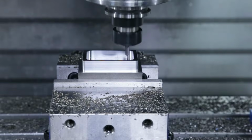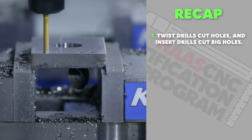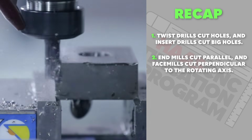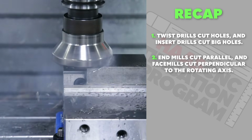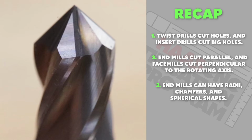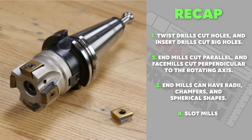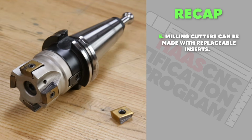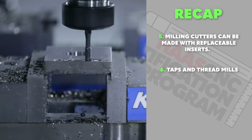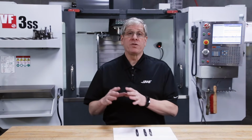So, that's a high-level overview of cutting tools. Let's recap what we learned. Twist drills cut holes and insert drills cut big holes. We learned that end mills cut parallel to the rotating axis while face mills cut perpendicular to the rotating axis. We learned that end mills can have radii or chamfers on the corners and can have a spherical shape on the end. We learned about slot mills and that almost any type of milling cutter can be made with replaceable inserts. We learned about taps and thread mills for cutting threads, and finally, we learned that there are different cutter geometries for aluminum and softer materials versus steel.